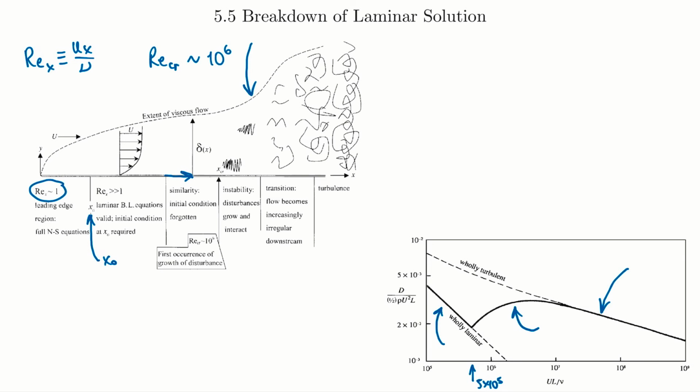Okay, now let's look at one more way we have to solve the boundary layer equations. In section 5.6, we're going to look at the von Karman momentum integral. Exact solutions for the boundary layer equations are possible only in simple cases, like the one we just did for the case over a flat plate. In more complicated problems though, one way we can do this is to see if we can find an approximate solution, right? So an approximate method will satisfy only an integral of the boundary layer equations across the layer thickness.